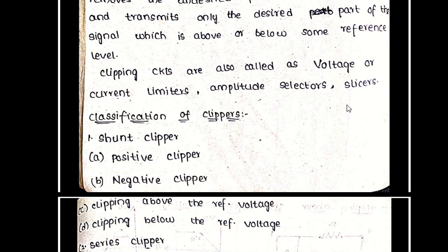That means in both circuits, the shape of the input waveform is altered. But in a clipper circuit, a certain portion is removed, whereas in a clamper circuit, the waveform is preserved, but it can be moved either upward or downward.